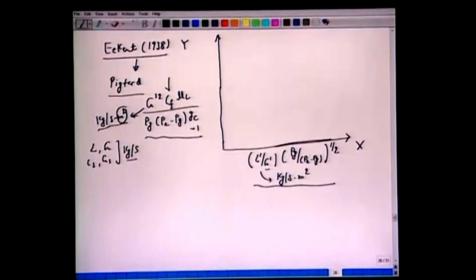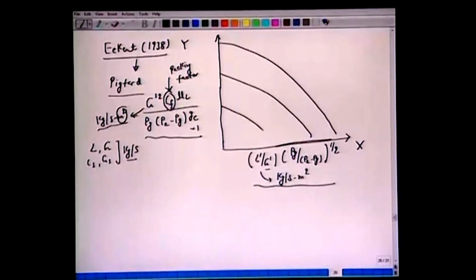Cf, if you recall, we talked about this packing factor. So the manufacturer or the handout of the packing which you have chosen should have given this Cf here. Okay, we have several lines here, like this, like this, like this. You will see the last line will be marked as the flooding line.